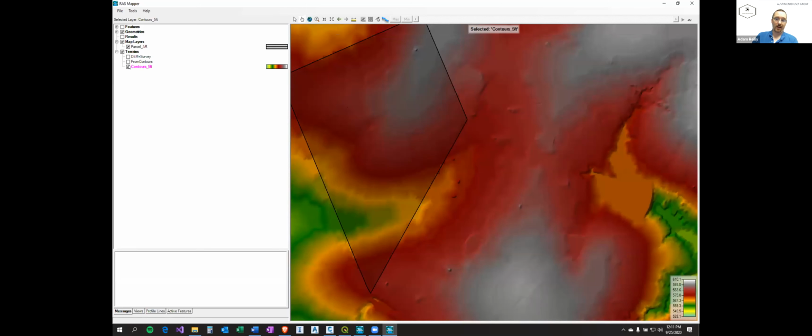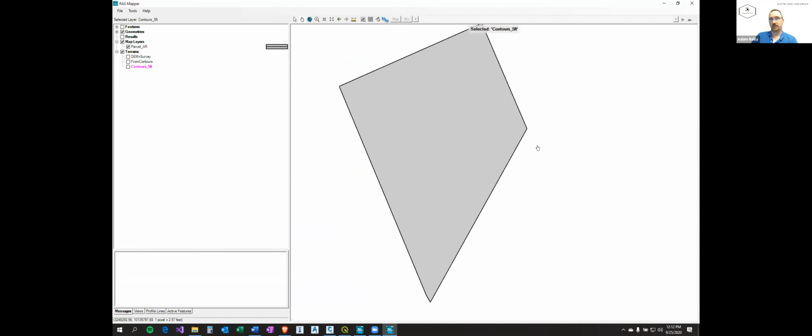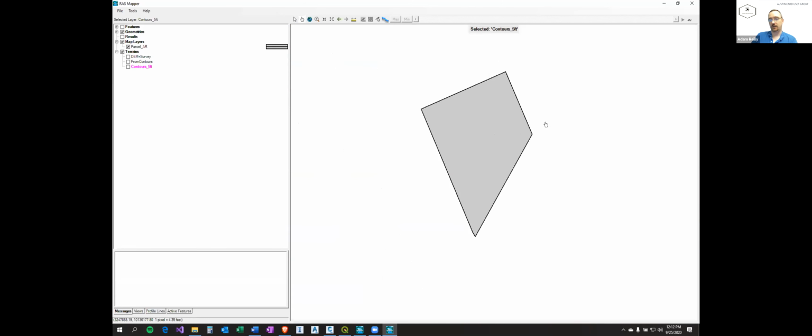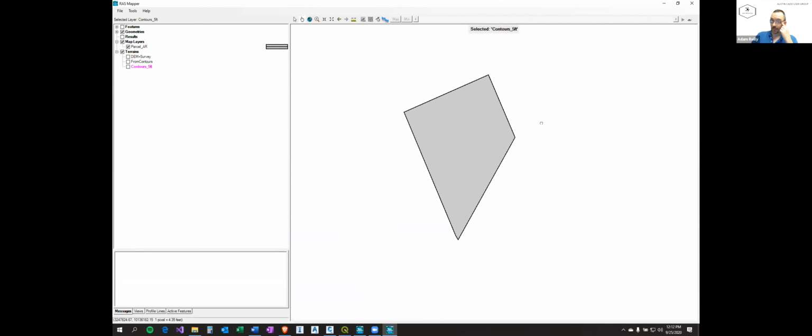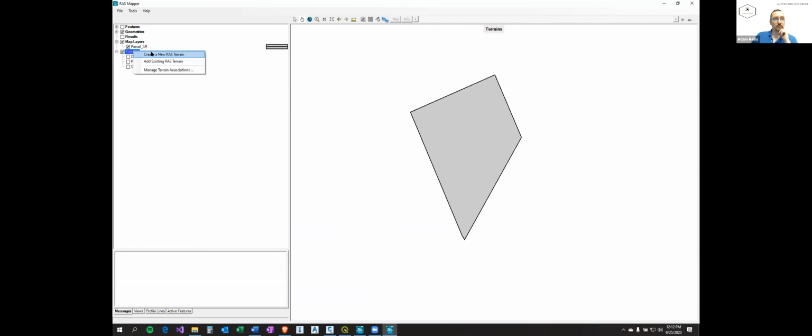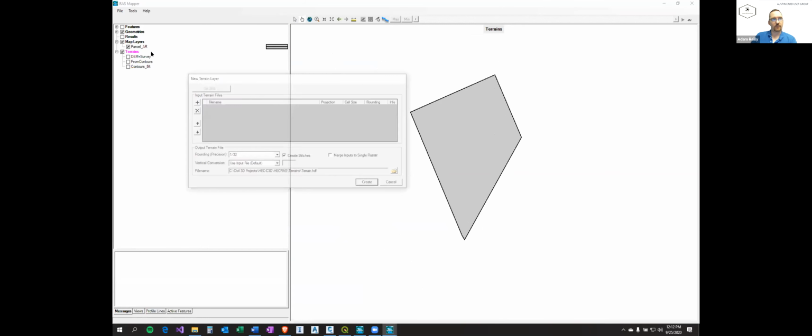So what I would prefer to do is go back to that original DEM data that I downloaded from TNRIS, and if I have survey data, even integrate that. So what I've begun to do is just splice them all together here in HEC-RAS because it does that really well. It lets you use different grid size surfaces in order to do that.